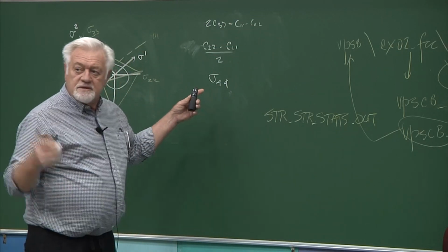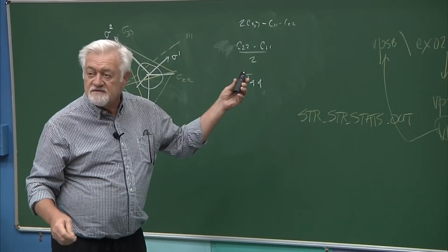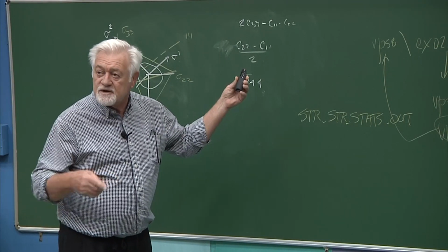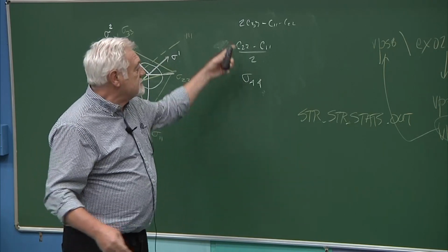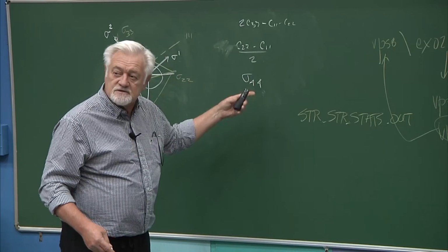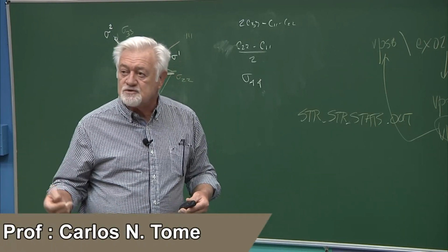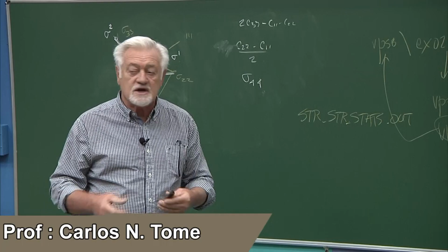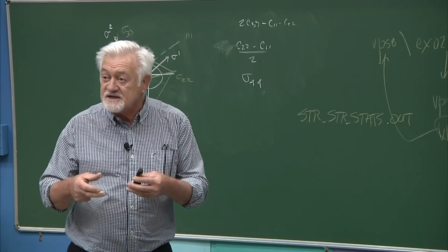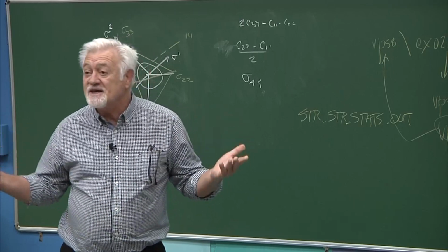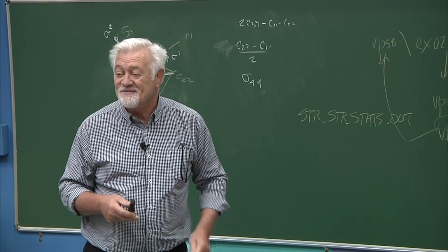Anyway, the B bases are the eigentensors of the stiffness tensor of a cubic material, and the eigenvalues are these values, and so it makes much more sense to work in that basis, because those are the natural resonant frequencies in cubic crystals. And they called them B, and that's what was adopted from then on.